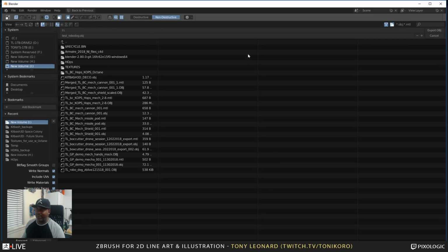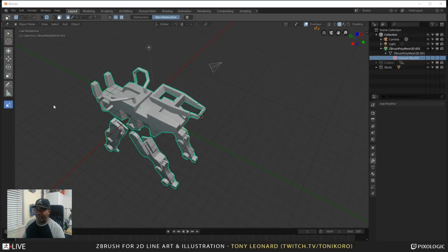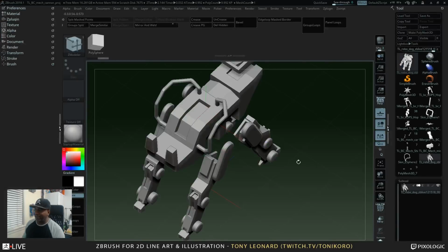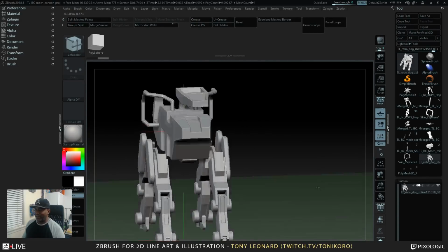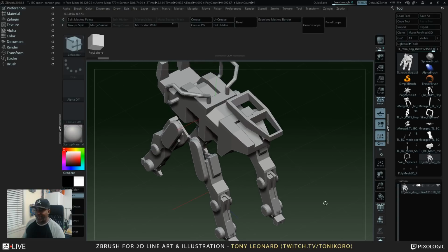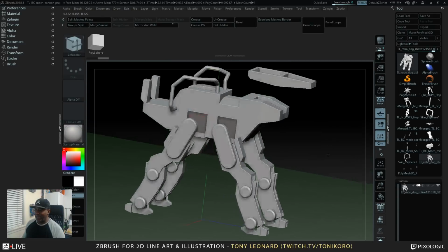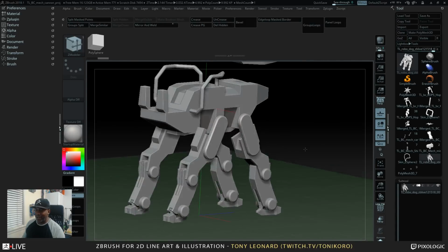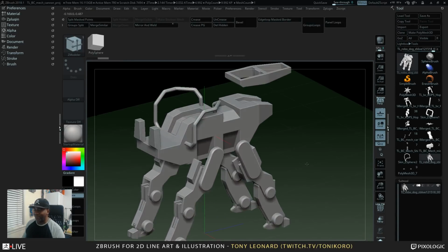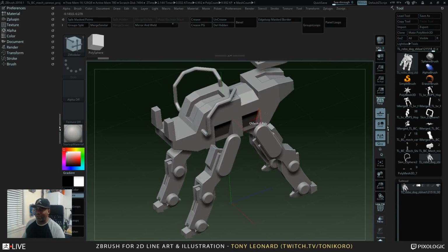So I'll save this out. I'll export it. Yeah, next time I need to figure out how to properly save between the two. I think there's something with that export setting that will let you export the whole thing that's been merged, but still be able to grab groups, but not split it by the actual polyfaces. Sometimes it'll unweld things, and what you'll get is a collection of all of your shapes that are unwelded. You can just grab the face and start moving around. You don't want to do that.